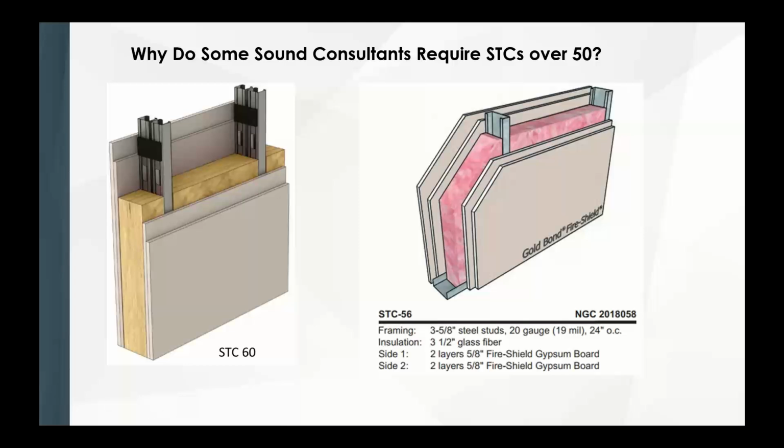Now, I'm posing a question here. You may have already seen this. Why do some sound consultants require STCs over 50? After all, 50 is code. Why are they saying 55, 60? The reason a lot of them say it is they're providing their client with belt and suspenders. They're telling their client, hey, there's a 5-point deficit that's going to happen if we field test this. That's just a common number that's out there. We want them to increase up to 55 so that when they field test, they're actually at a 50.